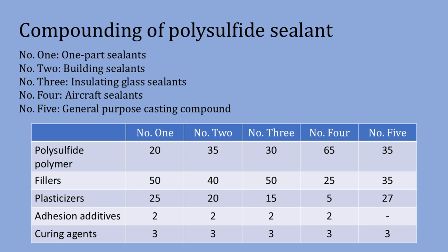Polysulfide adhesives and sealants are valued for their excellent workability, offering a smooth flow and superior electrical insulation alongside effective corrosion protection. These elastomeric compounds cure completely, often at room temperature, though sometimes slightly elevated temperatures are preferred, without any volatile emissions. They provide exceptional properties such as the ability to cure underwater, resist harsh chemicals, maintain high dielectric strengths, and deliver increased physical strength.